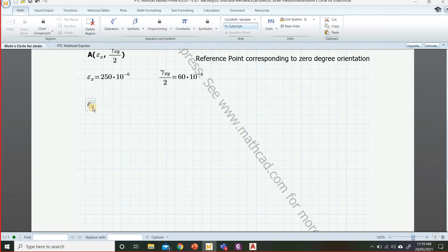Just bring them value those. If you like, you can, otherwise just pasting this circle is also enough. If you like, you can write these values over here. You will need to write these values because you need to perform some processing, not for the normal strain but for the shear strain, because what you have obtained from the circle is half of gamma x, half of the gamma max.